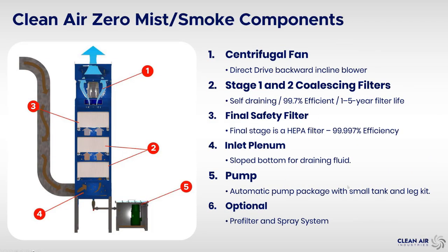So a little bit about how our collectors work. This is a drawing cutout, so you can see on the left side where the dirty air is coming in to the collector. You have stage 1 that takes anything from 1 micron and up and will filter all that out. It'll coalesce, drop down in the bottom, and you can see the little drain that goes down into a box. So we also offer a pump if you want to pump your leftover liquid or coolant somewhere else to use later or just to throw away.